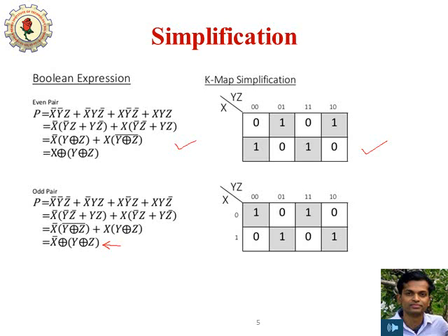Yeah, that's it. So this is according to property, I think, property 3. Yes, if we want XORing of the other inputs, what is the result? We just need to make one input negated. Okay, here we need the XNOR of the Y and Z. So what we'll do, we just invert the X bar. So this is the difference between the expression of even parity and odd parity.